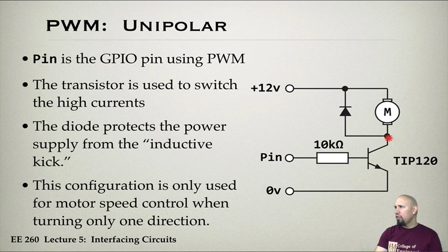The 12 volts is used by the motor, and the transistor acts like a switch. When this switch is grounded, I'm getting 12 volts going across the motor. This transistor can handle much more current than the other transistor we saw, the BCX38B.